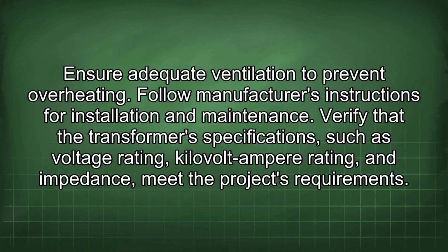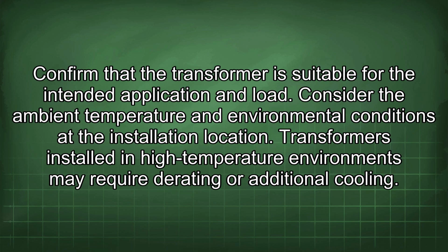Verify that the transformer specifications such as voltage rating, kilovolt-ampere rating, and impedance meet the project's requirements. Confirm that the transformer is suitable for the intended application and load. Consider the ambient temperature and environmental conditions at the installation location. Transformers installed in high-temperature environments may require derating or additional cooling.